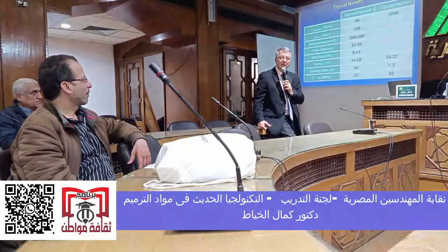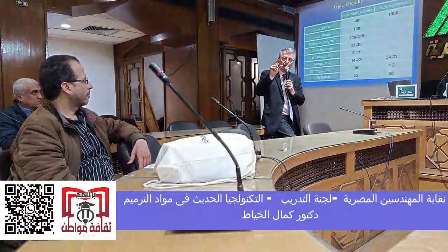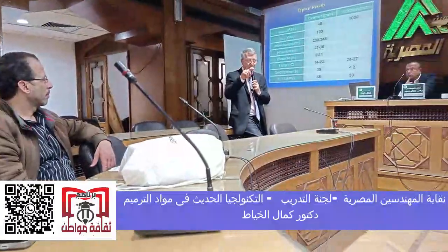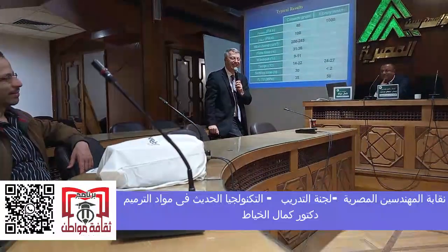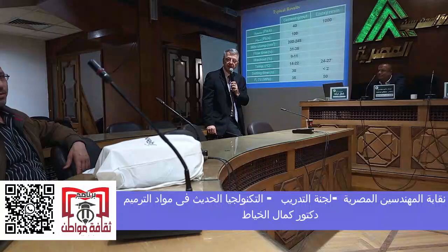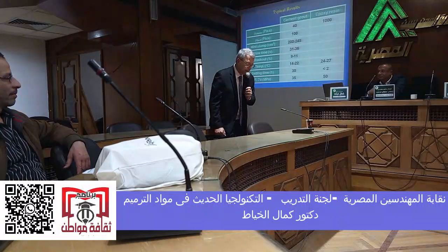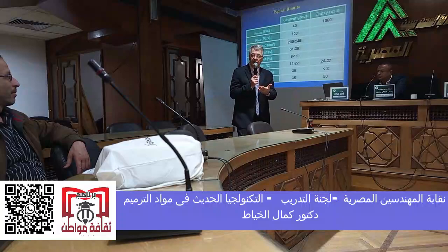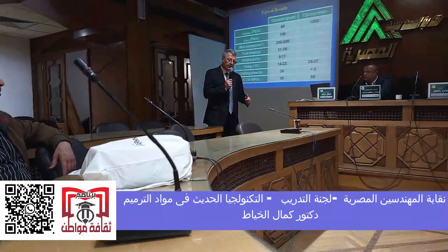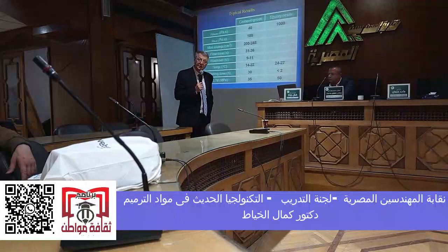But I expect that there are cracks in the middle also. There are cracks everywhere. So when they did the first mock-up and cast it, it was a slump of 1 inch, you can see through it. You can put your hand in it. Yeah, I mean, this was 1960 technology. They did not do it right. But you're right, you have to have at minimum thermal and shrinkage steel, and there was nothing here.